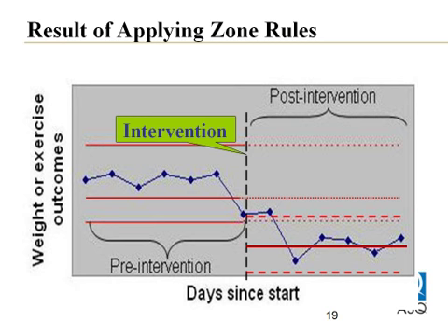Now take your hand away, and the intervention, the corrective action that's been introduced, has been completed, and now we're looking at the resulting data on the same process. And as you can see, there has been a major shift in the process going from left to right, and the center line of the process has been reduced significantly. The upper control limit of the post-intervention status is only fractionally above the lower limit of the pre-intervention status.